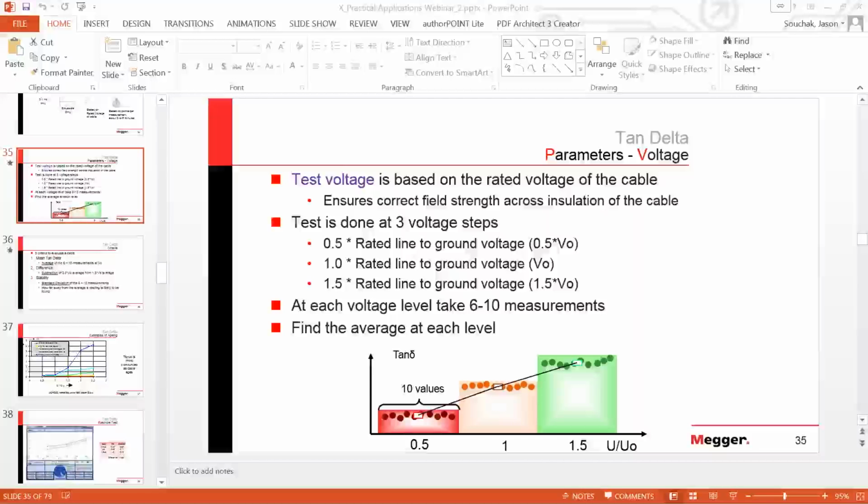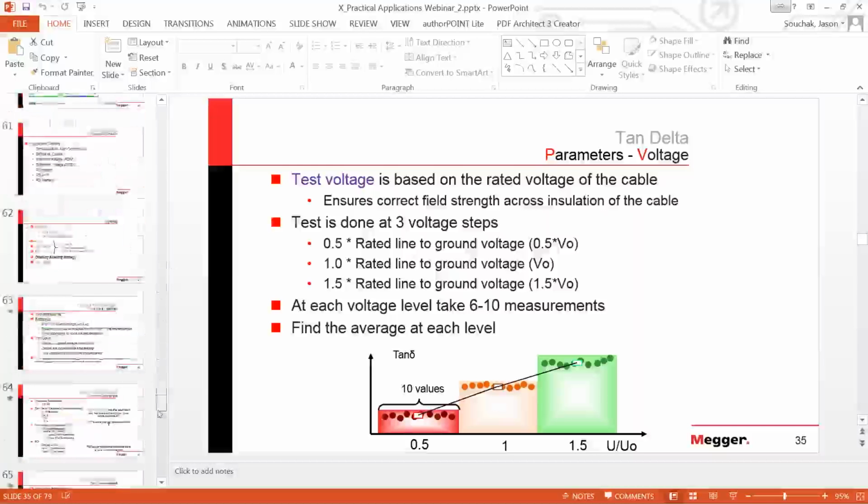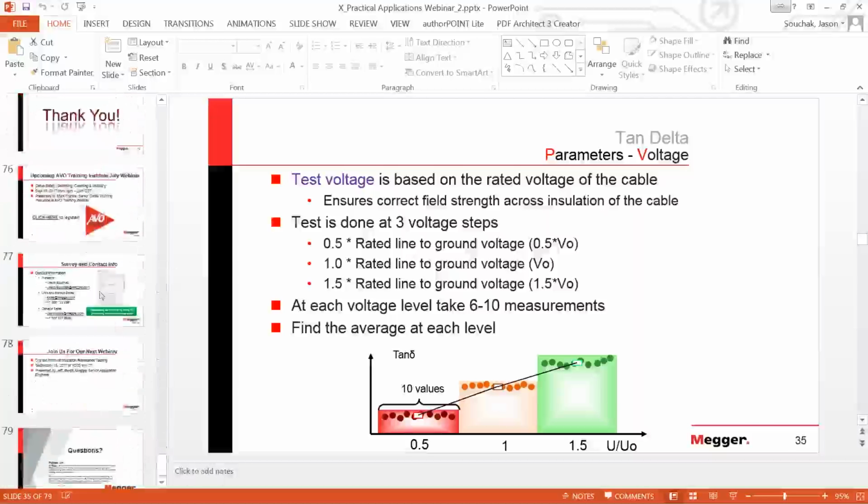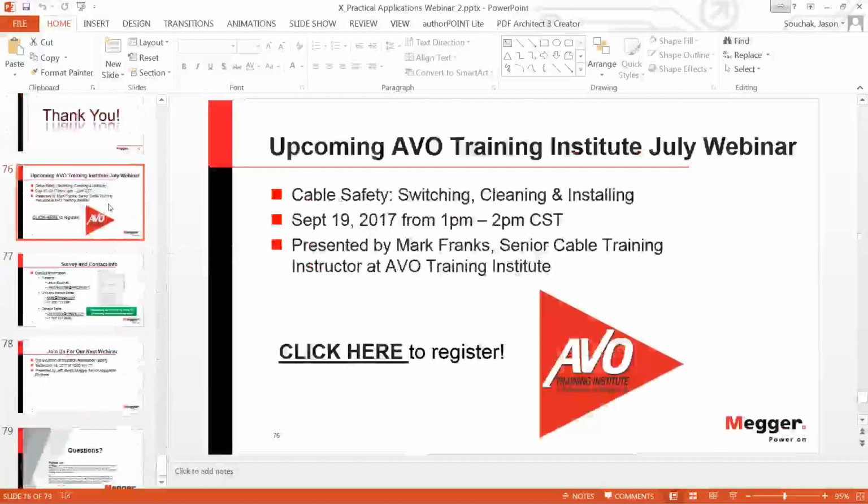And sometimes some cables are not always all the way buried. They might run in cable trays above ground somewhere. You have UV radiation from the sun, and obviously those cables see the UV during the day, and they have much more temperature change from day to night than a direct buried cable. So basically all these factors together in a given circuit will affect the aging of that insulation system. But temperature is obviously one of the very fundamental ones, and the higher the temperature, the faster the aging will go.